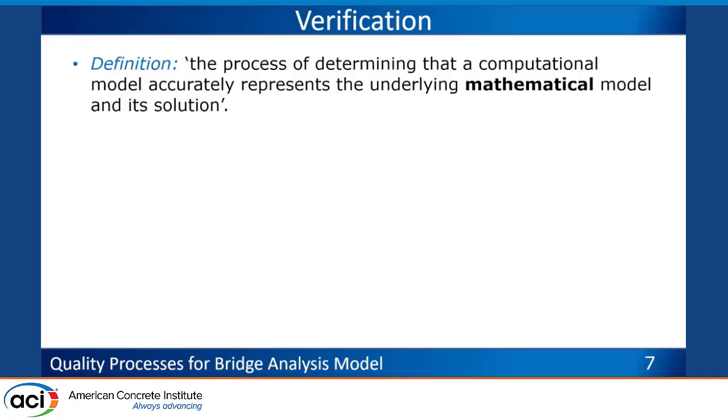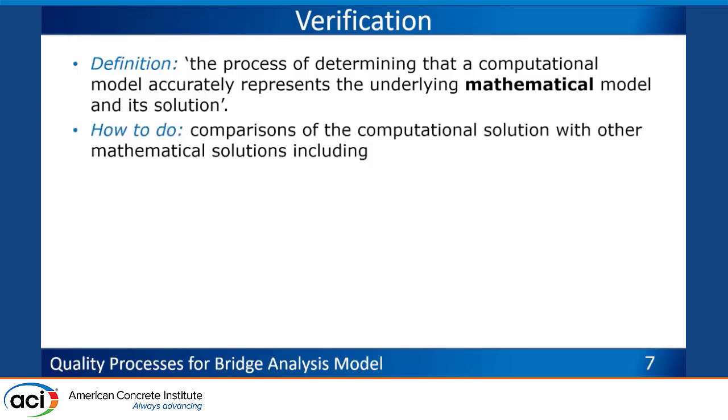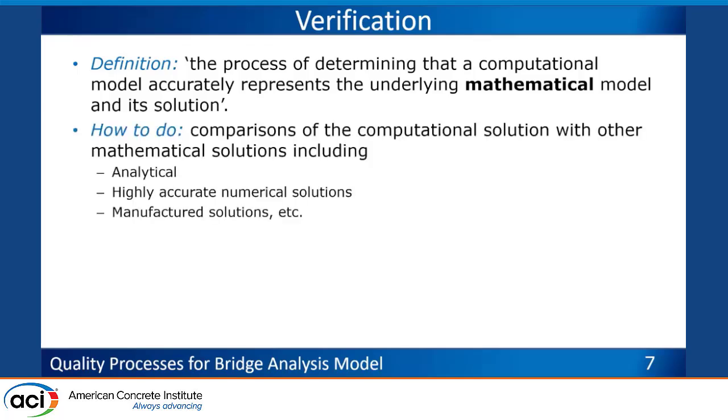Let's say you have a finite element model, but you can verify that using a strut and tie model. You can verify it with hand calculations or with some spreadsheet. So you are verifying it mathematically using a different method or different approaches. That could be sanity checks, independent calculations, line-by-line checking, refined analysis. So pretty much all activities that we do involve verification, right?